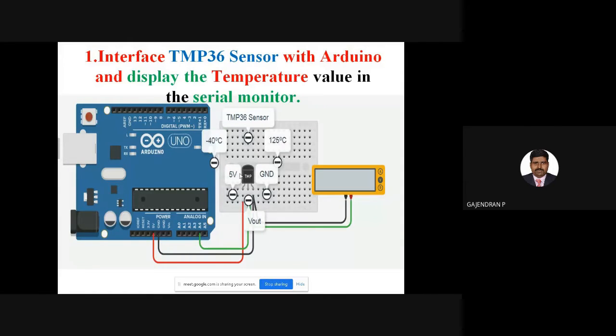This is your temperature sensor. You have 3 terminals. The left-hand side first terminal is the power pin. There we are going to give the 5 volt input supply. Then the last terminal, the third terminal, is the ground terminal. There we are going to connect our negative potential. Then the middle point is our output voltage. From that output voltage point, we are going to read the analog output from your sensor.